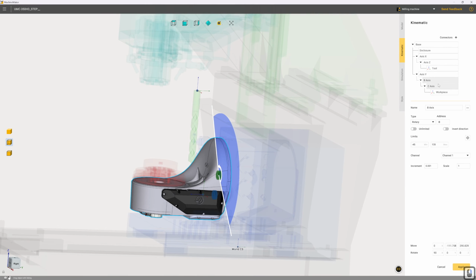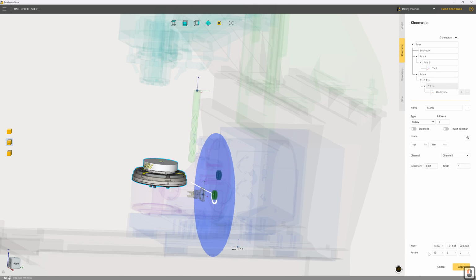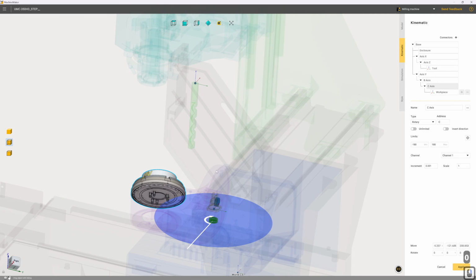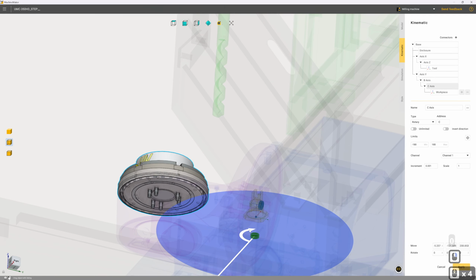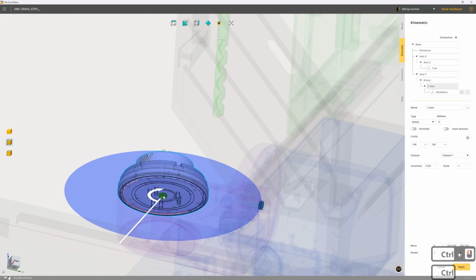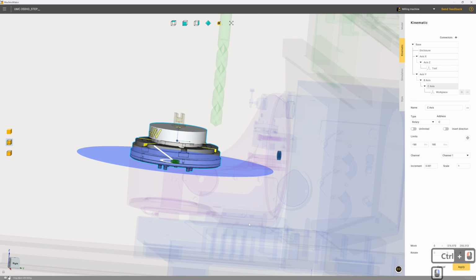So yeah, that's good. And then we're going to do the same for the c-axis, which we want to change the rotation back to 0 degrees in x, and we want to again snap it to the center point of this particular bearing plane. So hold down Control and move that accordingly, and we have got the full range of -180 to +180 motion there.